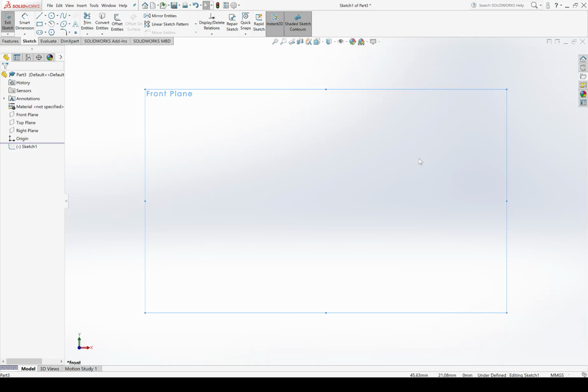The front view. All of the front view? Not the round shaft that sticks off to the right. Why not? I can add that later. Right. If I were to draw everything that appears on this front view, including that shaft that sticks off to the right, then when I sweep that through space, I'm going to have a weird rectangle sticking out the right side of my part. Now, I could remove material and leave the circle behind, but I could also just draw everything to the left of that part of the pin and then add that pin as an additional extrusion. Again, there's no best choice here. There's lots of paths to that end result.